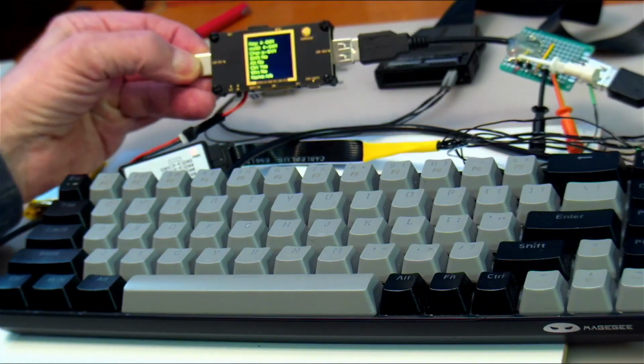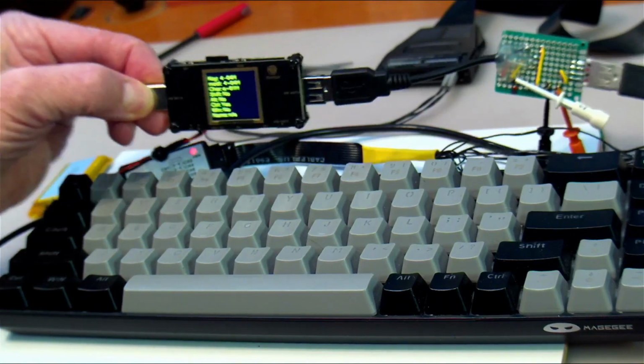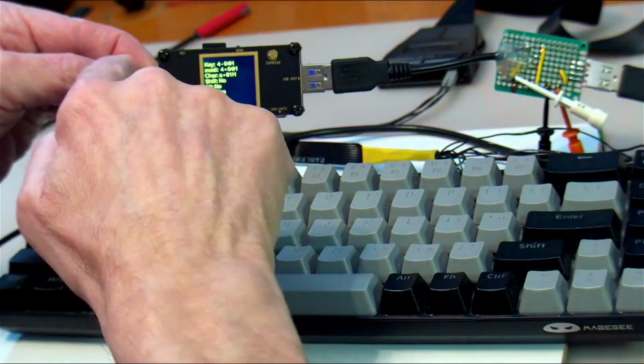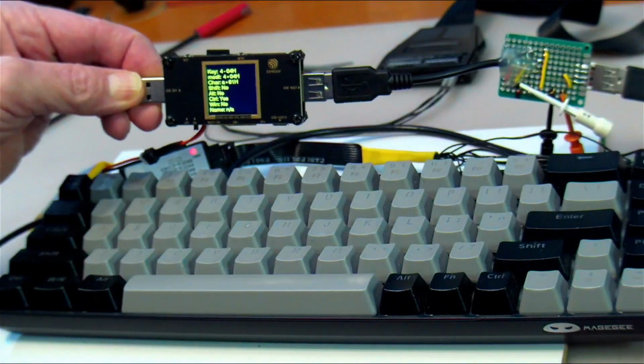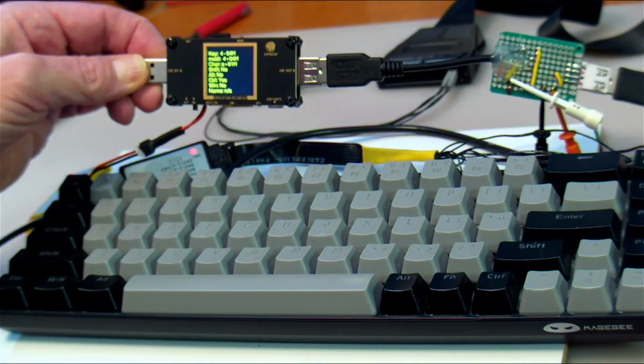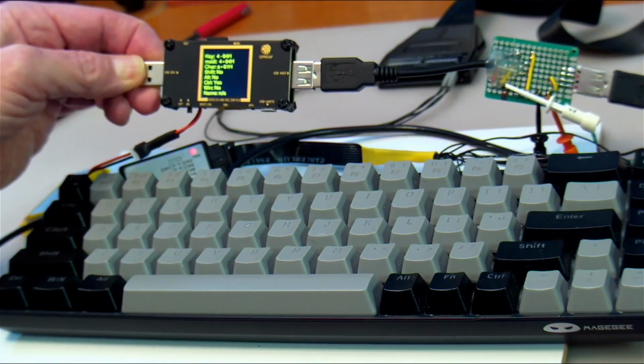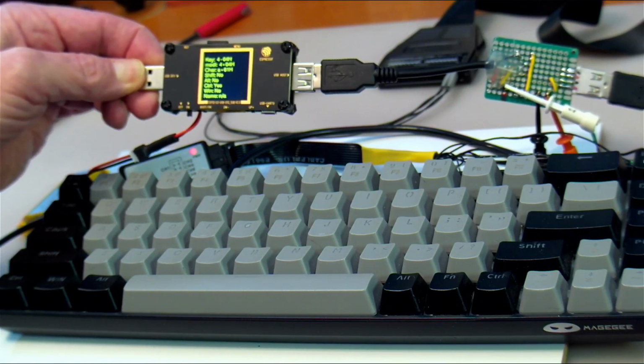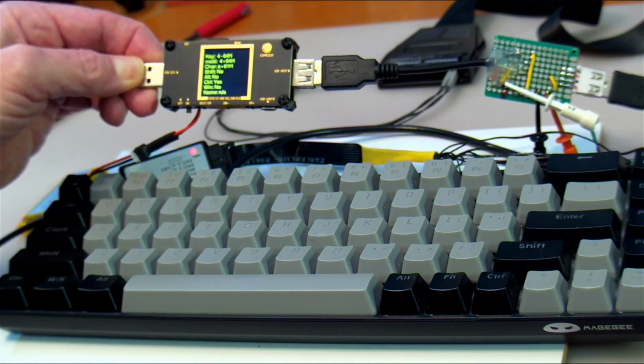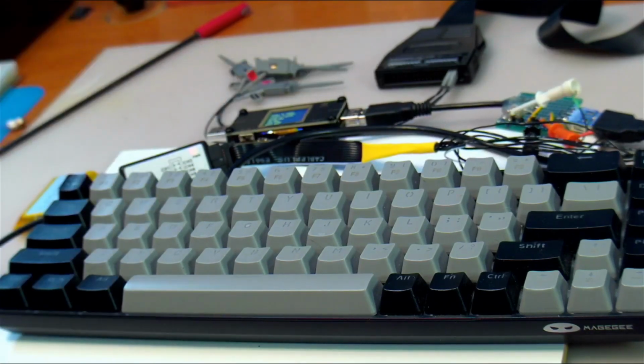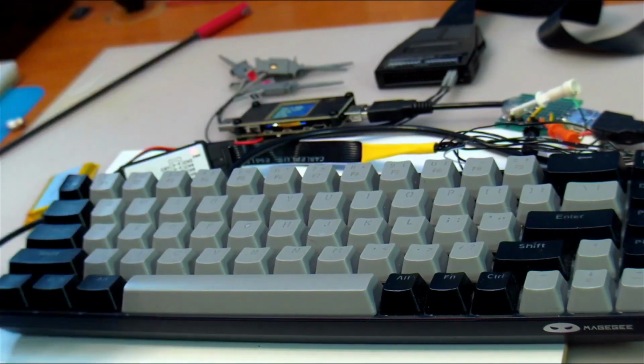They got two ports on them, a host and a device port, but they are using the same pins on the microcontroller for the D- and D+, so you can't use both at the same time. But one could potentially hang another one of these little USB boards onto it, which I must try, and if that works, I will certainly do a little video on that as well. Where is that thing? Is it in here?